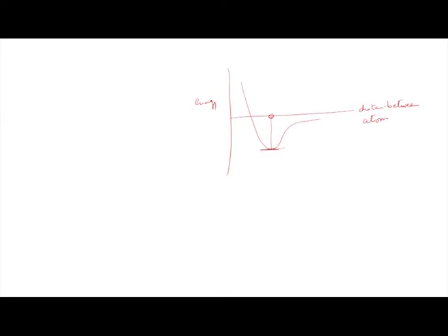So, as soon as I remove the force, it will try to go back to its minimum potential energy configuration, which is the equilibrium distance between the atoms. Okay. So, this is the driving force for elastic deformation.